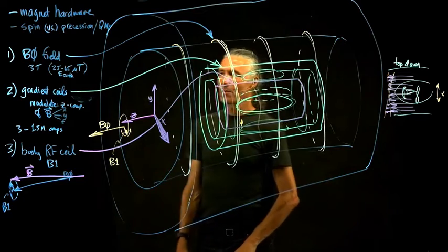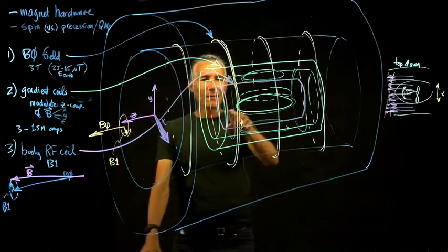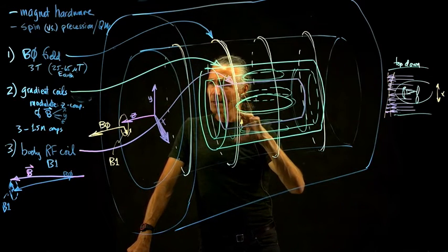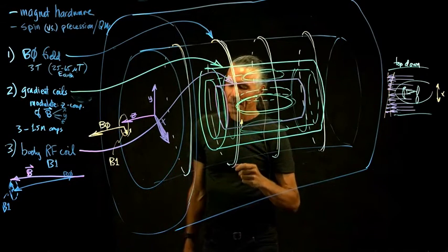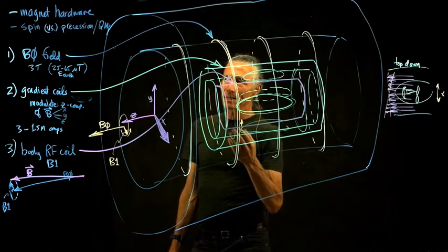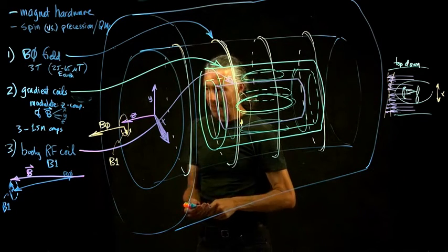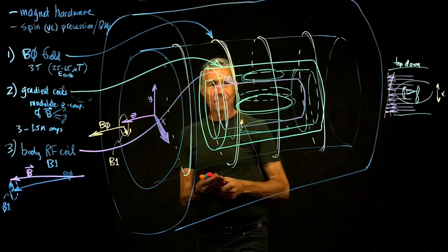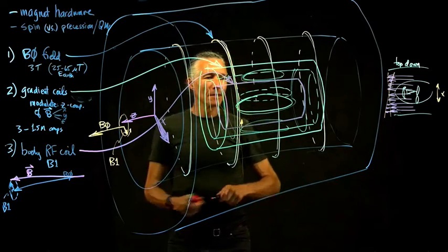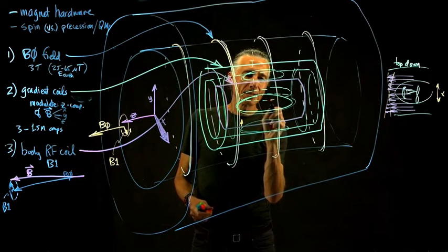And so we're almost to actually trying to get a signal. So that coil, that RF coil, will wiggle your protons a little bit. And then for about a tenth of a second, there'll be this little weak radio wave that will come out of your head from the wiggling protons. And so that comes out into yet another coil. So let's finally put the person in here.